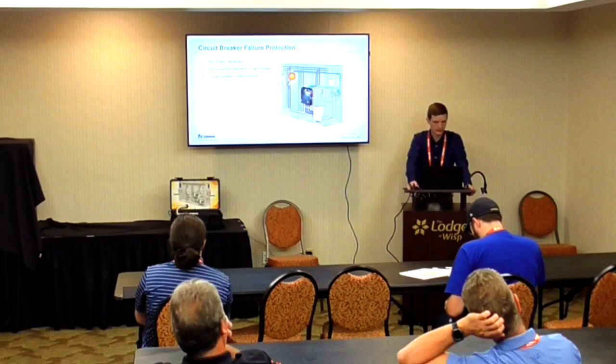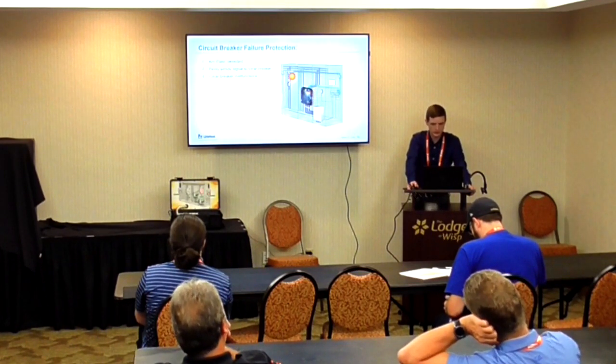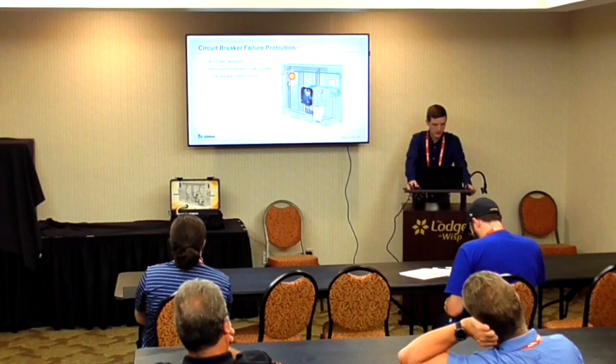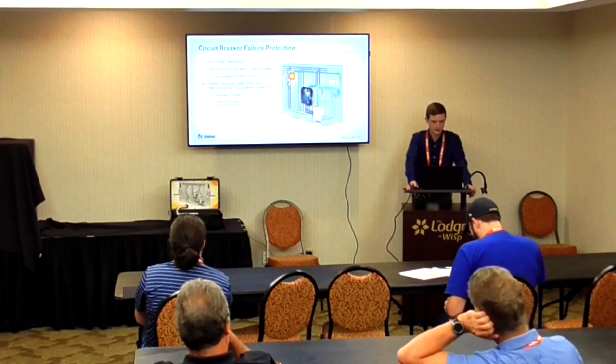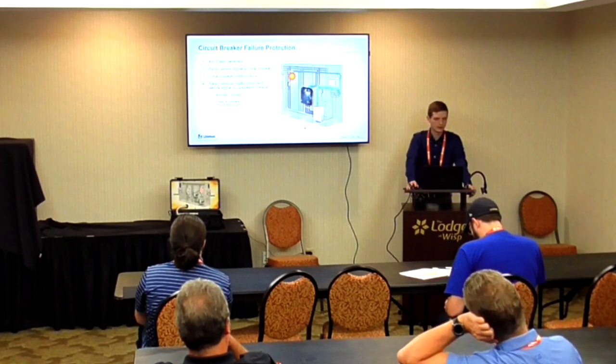If that breaker malfunctions, or if there's an issue with this equipment or this equipment, what it will do is send an auxiliary signal out to the feeder breaker. And then, ideally you won't have a fault there as well. The odds of that are very minimum. So we've got a redundant safety feature built in here.